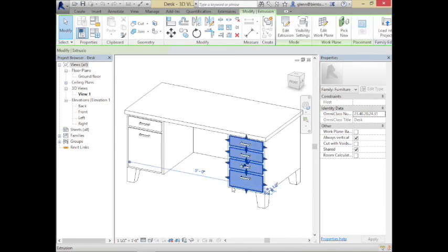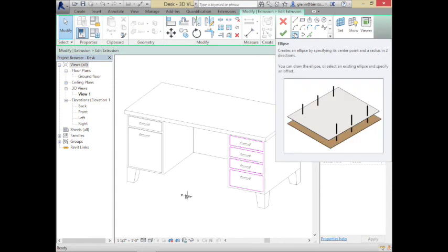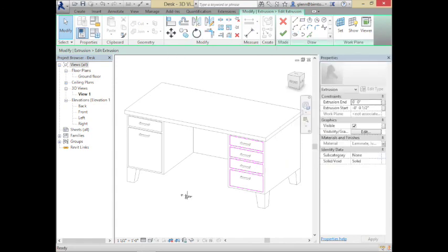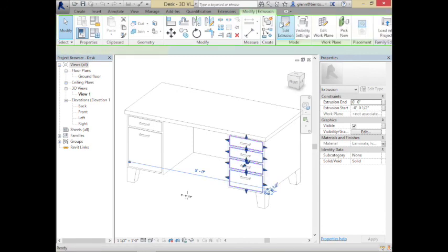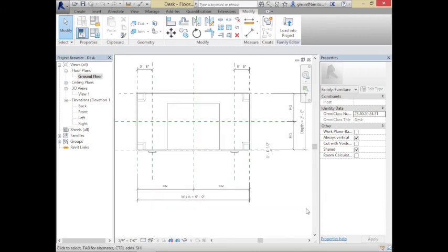Yeah. I'm betting those are an extrusion, but notice this. They're not extruded from the ground up. They're extruded from the face back. And so how does this all work? In terms of why does that desk resize and do what it's supposed to do? If we go back to the definition, you'll see it actually has these reference planes too. The depth is 2'6", the width is 5 feet. So what happens is the body reshapes as it needs to. These little corners are aligned to the edges of those green lines. That's why they pull out where they need to be. What's this 8 inches? This 8 inches is, I think, the space to wherever the drawer front is. So the drawer fronts are always 8 inches from the corner.